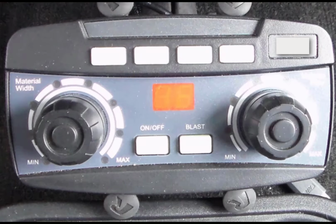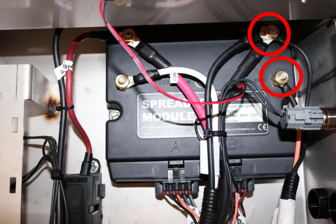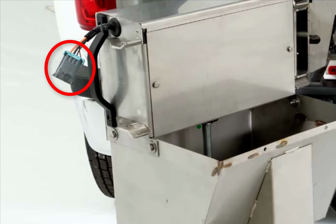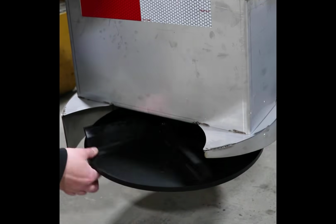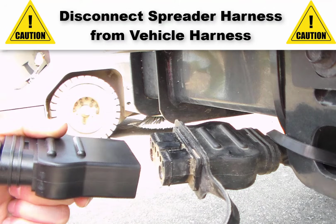If the control is flashing a SO code, the module is sensing that the spinner motor is drawing too much amperage. Check the connections at both the motor and the spreader module. Make sure all connections are tight and free of corrosion. Visually inspect the wiring to ensure there is no damage. With your hand, grab a hold of the poly spinner disc and see if you can spin it with ease. For your safety, disconnect the vehicle harness from the spreader harness before performing that check.